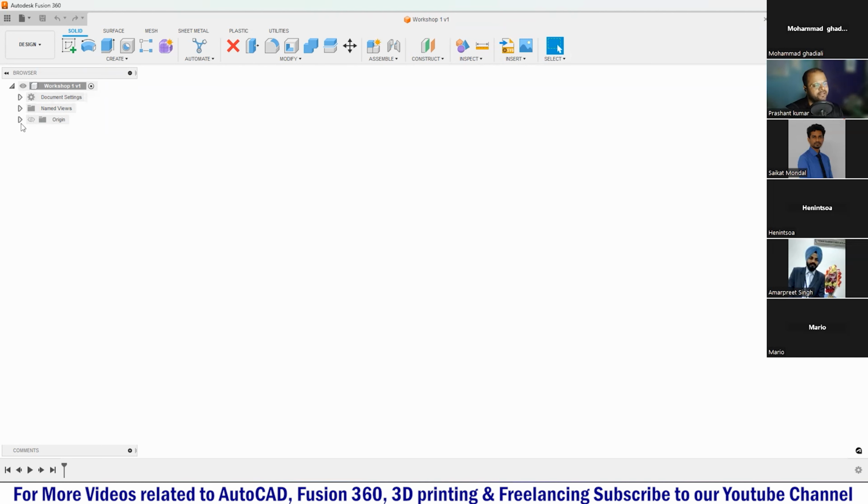The moment you create a sketch, a sketch folder will be created. The moment you create any solid model, those folders will be created. The moment you start creating assemblies, the assemblies and mates folders will be created. So this is basically a design tree, and every step will be getting saved.